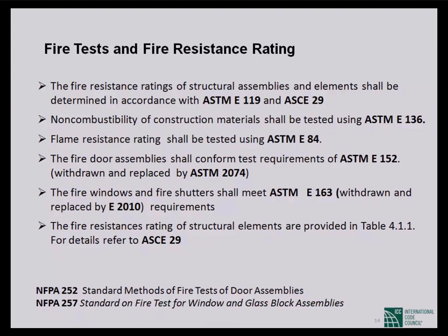Then this chapter contains something on fire test and fire resistance rating, which is very deciding. Here are some standards. I shall talk in a little bit of detail about these standards, how they are tested, how the testing can be explained. So you can see here is ASTM E119. Using this standard, we test the structural elements and the structural assemblies. It's elements as well as assemblies.